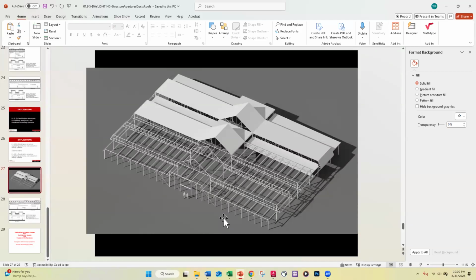Now, some of this substructure, like these beams, and some cross bracing associated with those beams, would probably be crucial to keep the building aligned and stable until the corrugated decking can get screwed down. So you're not going to be able to get rid of all those purlins and all that substructure, but you will significantly simplify it if you run the corrugated decking between the trusses.